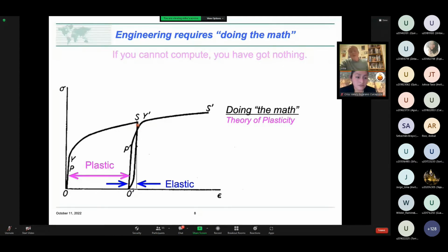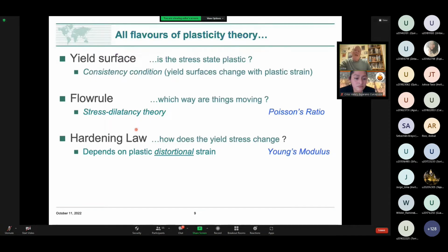When you take a piece of metal and bend it and permanently deform it, it deforms because dislocations between the metal crystals have moved. In soil, as particles move, we make and break contacts between the particles, how they touch each other. Mathematically, it's much the same thing, which is why the theory of plasticity works for soil as well as metals.